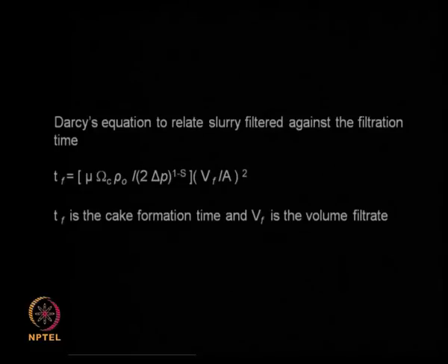Remember that cake is formed only when the drum is dipped inside the slurry tank, whereas when the drum is outside the slurry tank there is no new cake being formed; the cake is getting washed, dried, and cut.